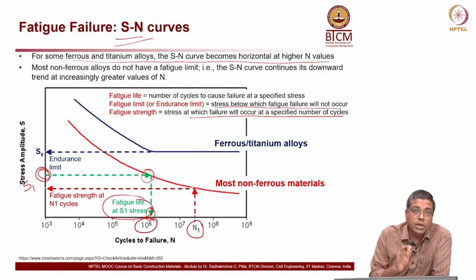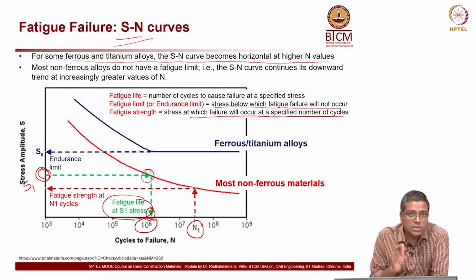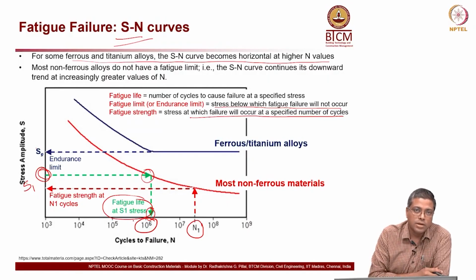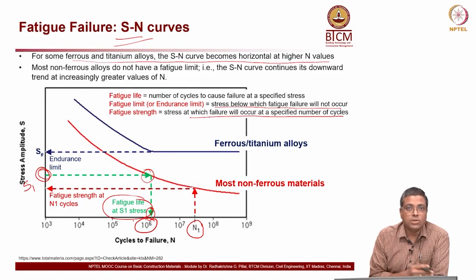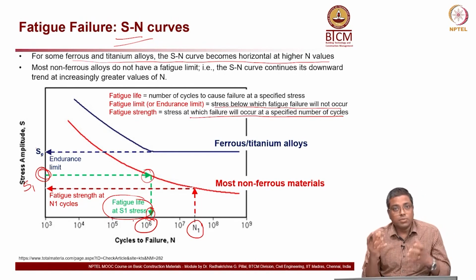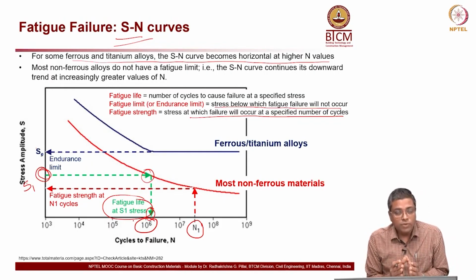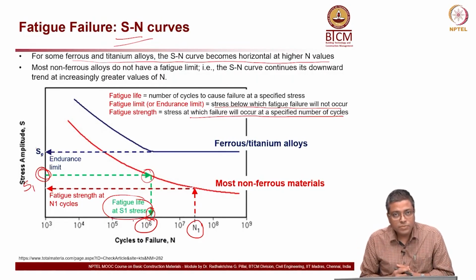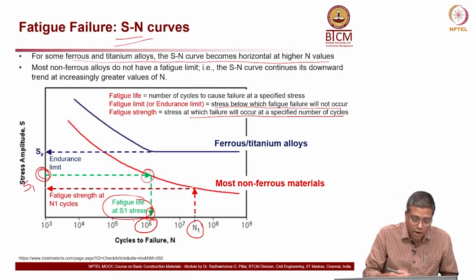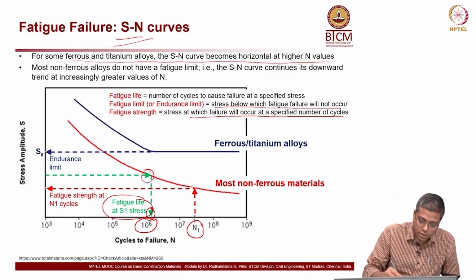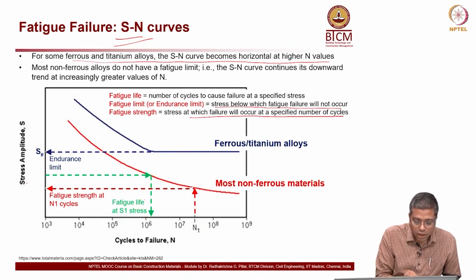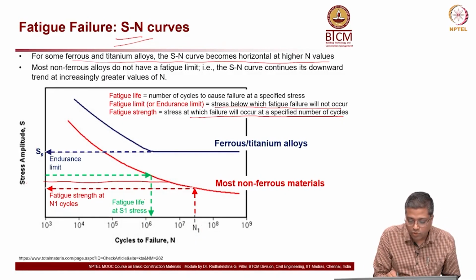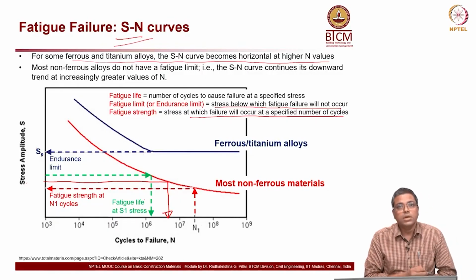Now, I can say how many cycles the structure has already experienced and what the remaining cycles are, because I know that if the current load is being applied, it will not stand beyond 10 to the power of 6 or approximately that. So, as the person in charge, if the life of the structure needs to be extended, you have to reduce S1, okay, and probably start somewhere here and then go further and make sure that it gets more life.